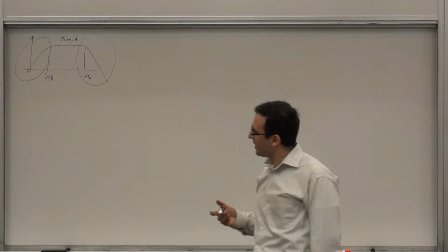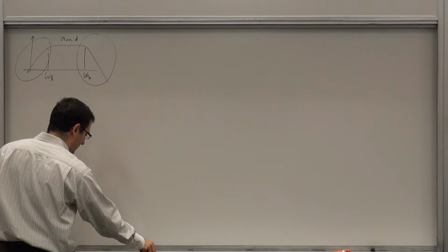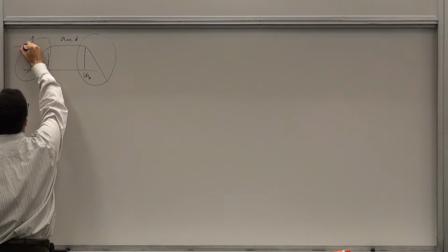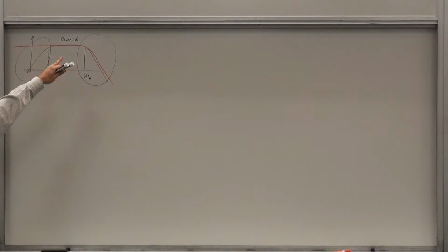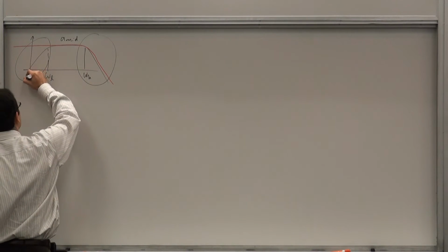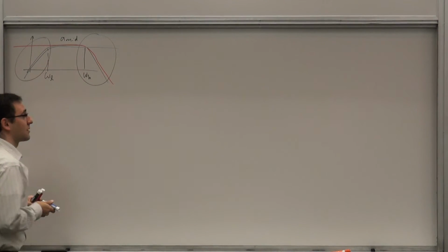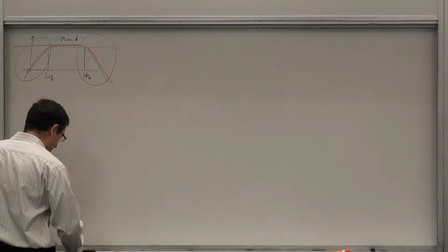So, in general, so far we've been thinking about the following: if you had something like that, we've broken it into two parts, and we looked at the red part of the response. That was why we were talking about the zero value time constant frequency estimation. We said it's a low pass system, and just looked at that equivalent circuit. Now, there's another equivalent circuit, which is the high pass equivalent circuit, the blue one. You can do a similar treatment of that, and that allows you to estimate this frequency. So let's see what it looks like.